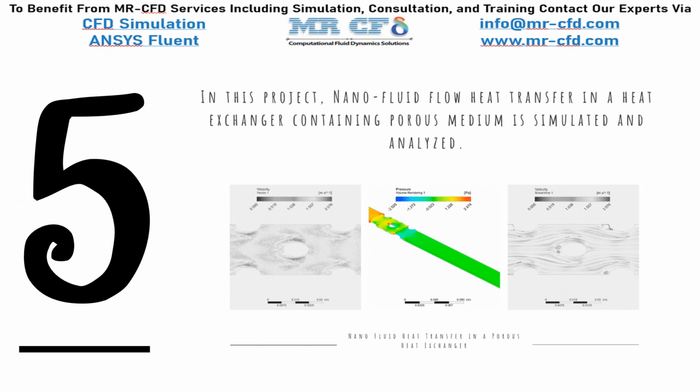In this project, nanofluid flow heat transfer in a heat exchanger containing porous medium is simulated and analyzed by Ansys Fluent software. The energy model is activated and the Spalart-Allmaras model is activated for solving the turbulent flow.